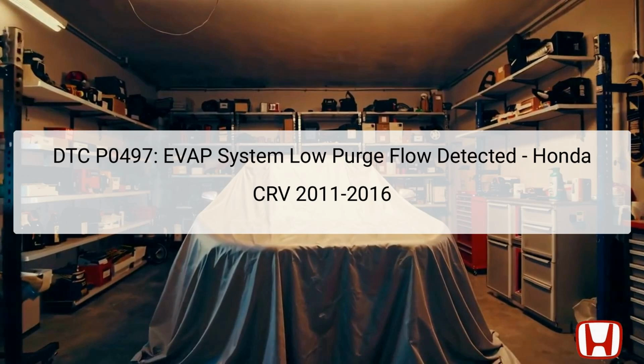In this case, the low purge flow suggests that there could be a blockage or a malfunctioning component, preventing the proper release of vapor pressure. During the diagnostic process, it is imperative to utilize special tools, such as a vacuum pump gauge and a vacuum gauge, to accurately assess the system's condition.